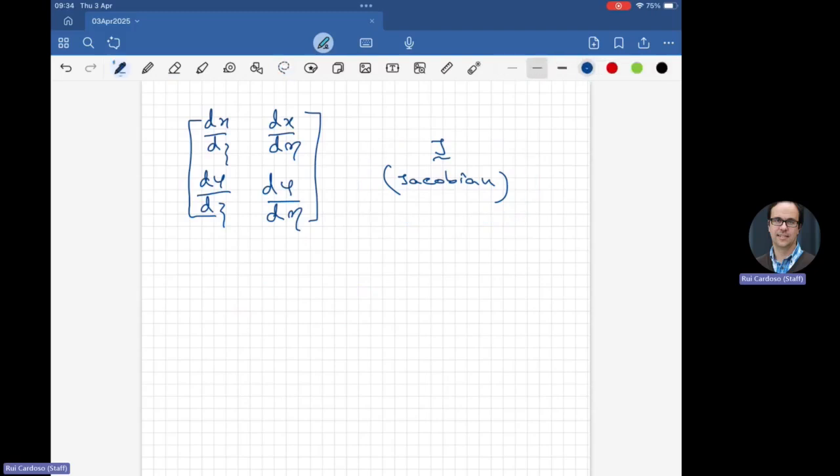Yeah, exactly, very good. So how are we going to obtain this? Look how easy this is going to be. I told you that we can obtain the x coordinate by multiplying the shape functions with the coordinates at the nodes. I can do this for x, I can do this for y, right? You agree with this? It's interpolation, right? And now look at this. What do I need to have in my Jacobian? The derivative, for example the derivative of x.